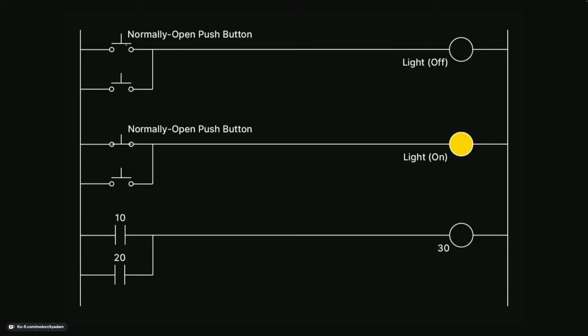What these two rungs up here represent is the physical situation. You can call this a push button, right? I'm pushing on the top of this part here, and it pushes down this line to make a connection. And you can imagine some voltage. Maybe this is 24 volts over here, and this is ground. When you push the button down on either of these buttons, current will flow through this wire and the light will turn on. So that's represented here. You push down the button, current is now flowing through here, and the light output turns on. So input button, output light.